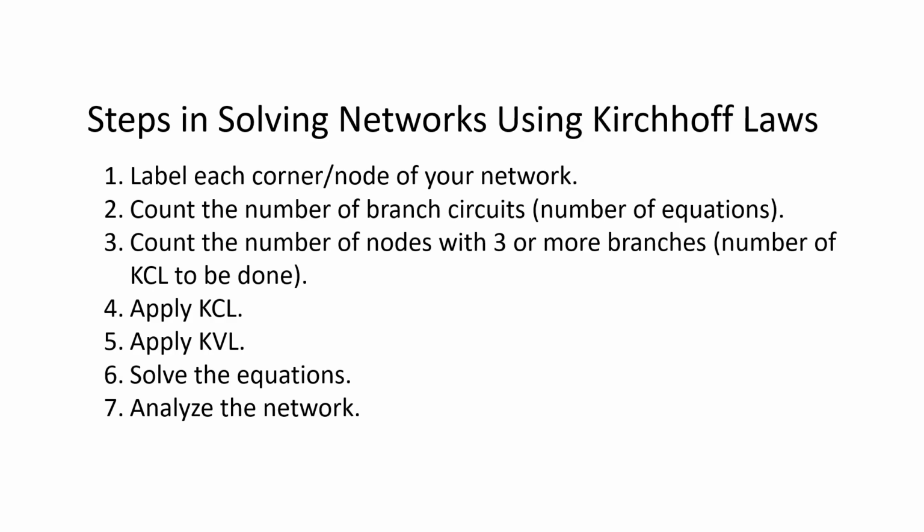Then second, we'll be counting the number of branch circuits, as it will tell us the number of equations. Remember, the number of branch circuits is equal to the number of equations when using Kirchhoff's laws in solving electric networks. We also need to count the number of nodes with 3 or more branches, because that will tell us the number of KCL equations to be done when solving such a problem.